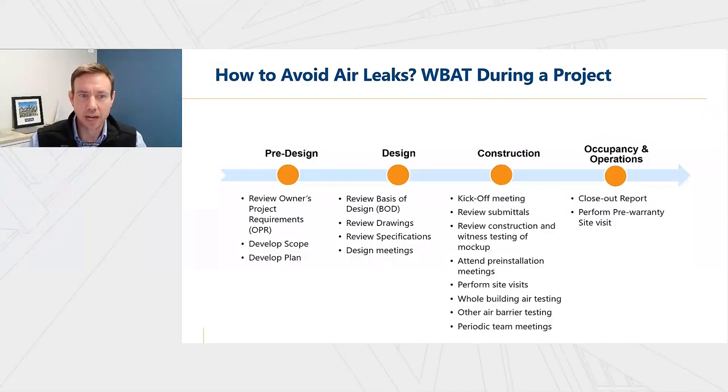Constructing and testing a mock-up with an air barrier to review installation and testing performance before implementation on the building is very beneficial. Then periodic site visits during construction and testing to validate performance is important. And this is where whole building air leakage testing occurs, once the entire air barrier system is installed.